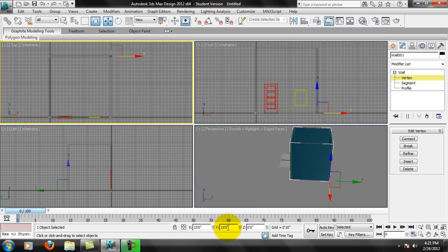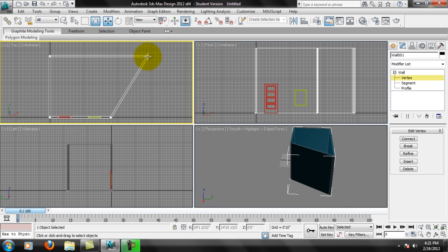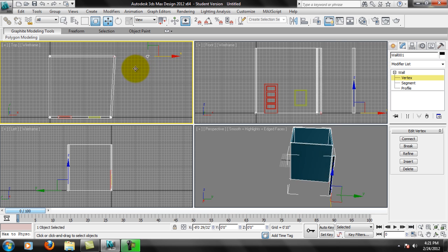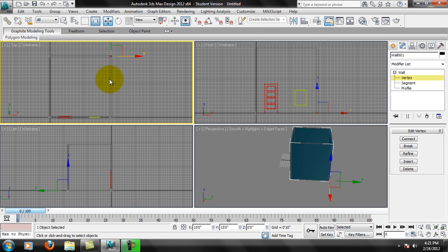So if you need to come back to it, you can type it in, because you can notice here once I start moving that point, now I have a different point, and it's almost impossible to click this back to 15 feet just by moving. With grid snaps, I could do that. I could actually type it in if I remember. That's why I say write it down, and I can just type it in, and I'll be back to straight there.